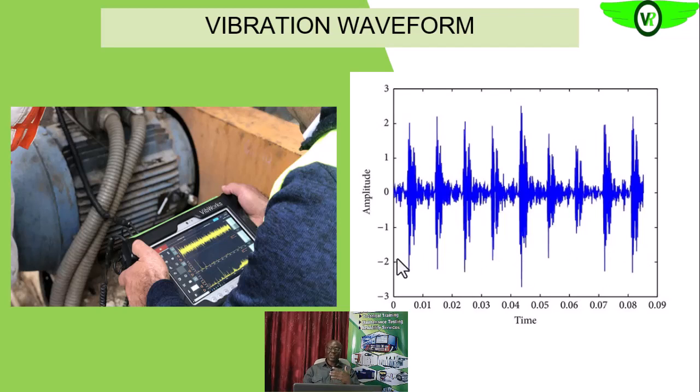But what is actually causing this vibration? Like we did in the voltage waveform, we can do a fast Fourier transformation on this vibration waveform, and that will be able to separate each of the vibration waveforms that we have into their respective frequencies. And the beauty is that various fault conditions in the electric motor, and even on the pump, appear at different frequencies, as we will see later.